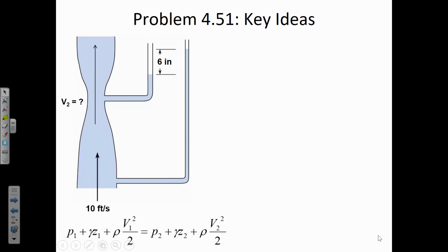We have a venturi. And this is what we're going to look at in the lab today and tomorrow. In a venturi, it's a pipe where the diameter constricts so that the velocity goes up, and then the diameter goes back to normal again. So it's just a temporary restriction in the throat of a pipe, and that temporary constriction increases the velocity and decreases the pressure.